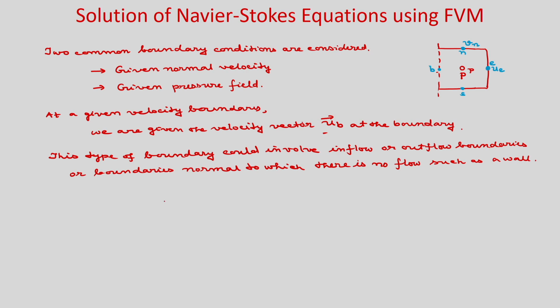Okay. So, let us consider a channel. Let us consider flow between two parallel plates. The third direction is infinite. If you want to give the velocity boundary condition, then on the walls there will be no slip, so velocities will be 0. At the inlet you can specify a uniform velocity boundary condition, or some time varying or spatially varying boundary condition.